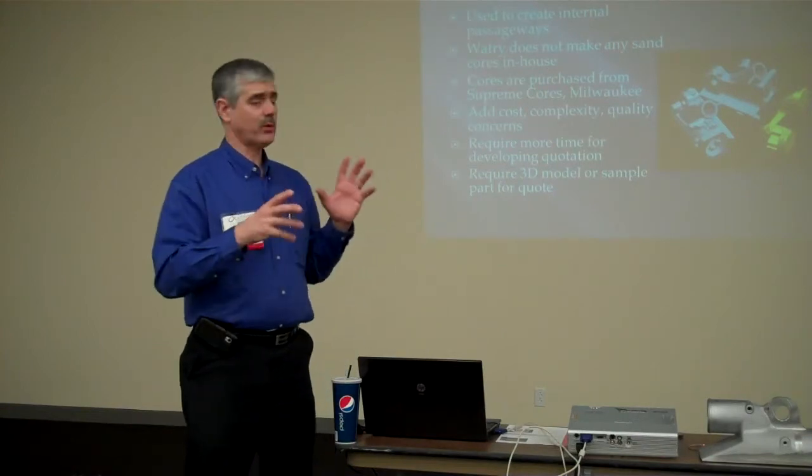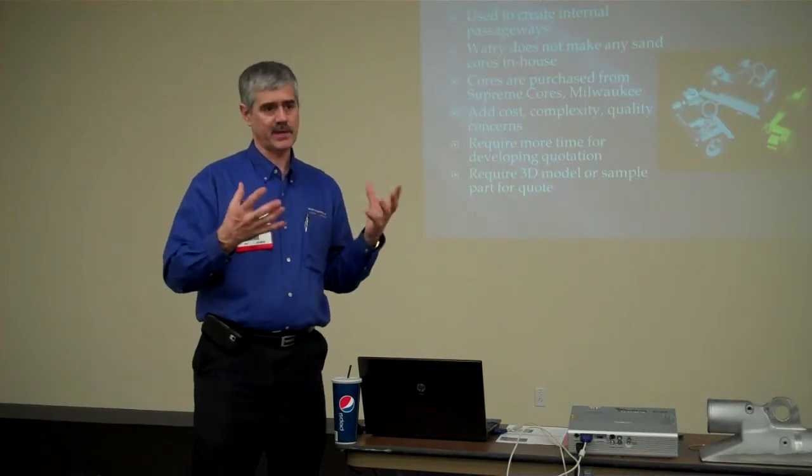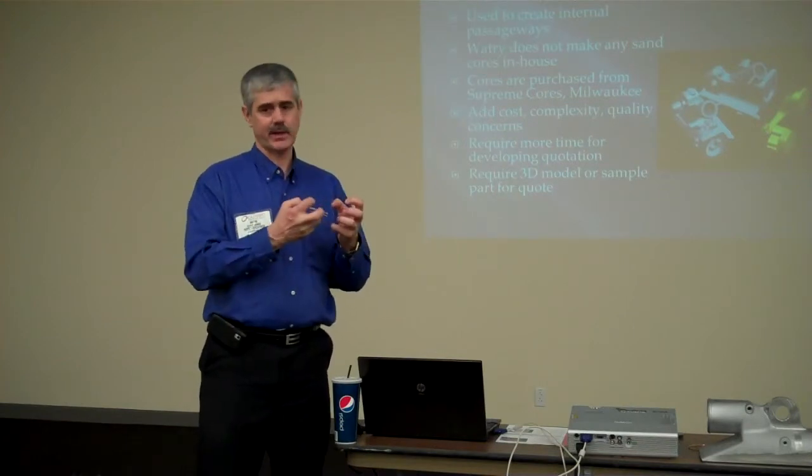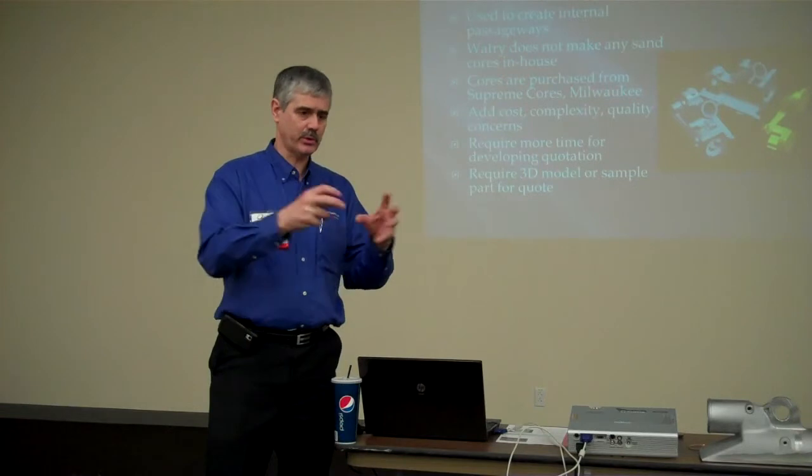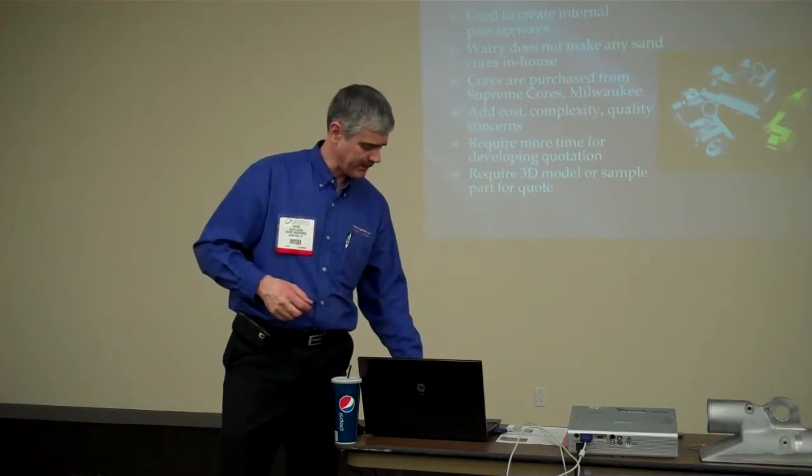I'm not going to really go into the whole core blowing process, but it's a chemically bonded sand, and then the sand holds together like a cement block, so to speak, and you pour aluminum around it, and then shake it back out of the part.